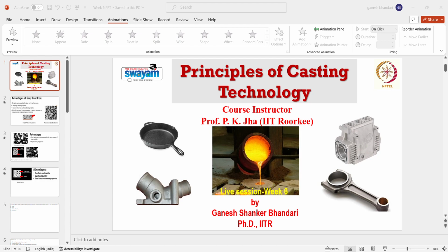You can say that during heat treatment, or when you go with the casting process, maybe with continuous casting, you can get white cast iron. If you go with a very low conductivity type of mold, that is, your molding process uses a very low conductive mold, the solidification time will increase. If you increase your solidification time, you will not get rapid cooling rates, so you are going to get gray cast iron.